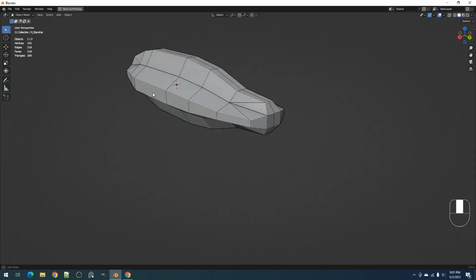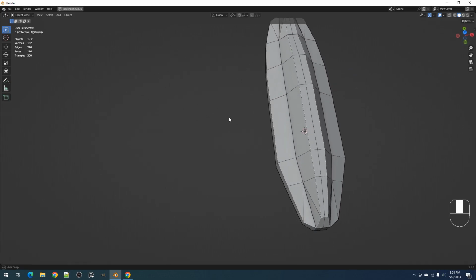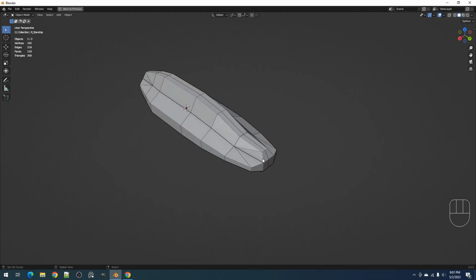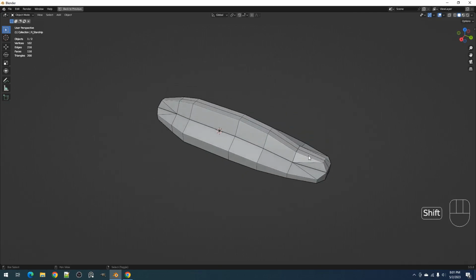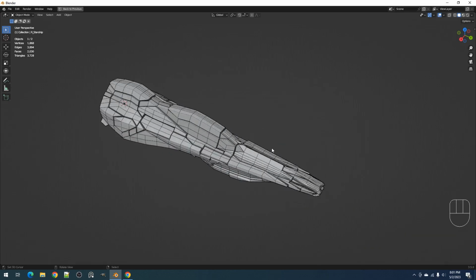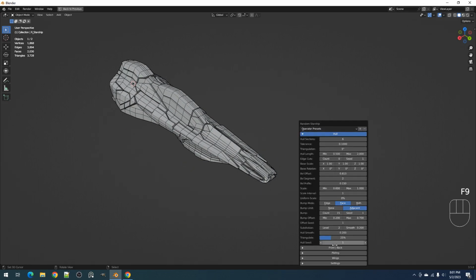The smooth property allows you to add smoothing to the front or back of the ship. Its main purpose is to unflatten the front and back of the base geometry so the bumps and plating details can have better results in these areas. I'd usually go for a value of 1 or 0.5. Using too much will eventually lead to overlaps, so be careful.